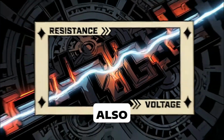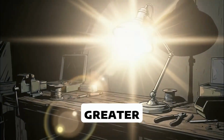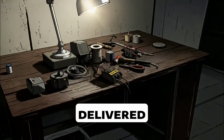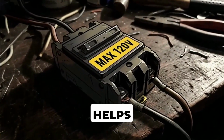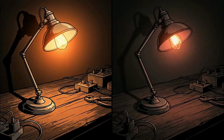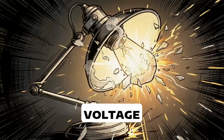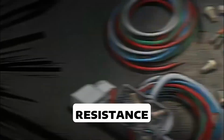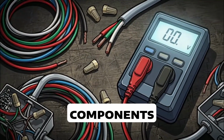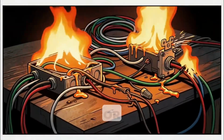Power and work are also tied into these relationships. Current is energy in motion. The greater the current, the greater the energy delivered to the load. But that only helps if the parts are rated for it. A 120-volt lamp may glow normally at 120 volts, glow dimly at 50 volts, or burn out if too much voltage causes too much current through its resistance. In other words, components are designed for specific voltage and amperage ratings. Exceed those ratings and they can overheat, melt, or catch fire.